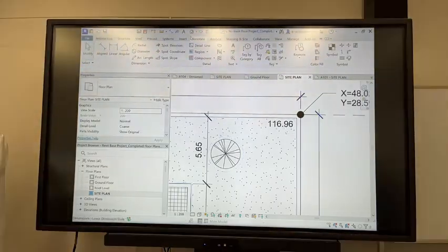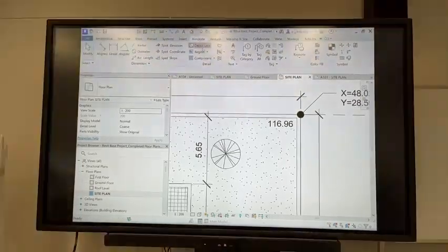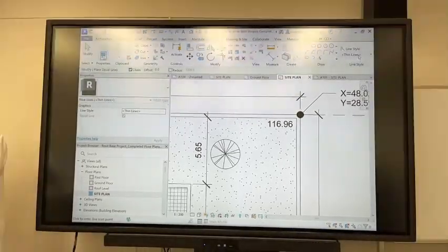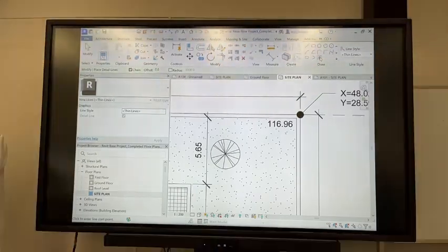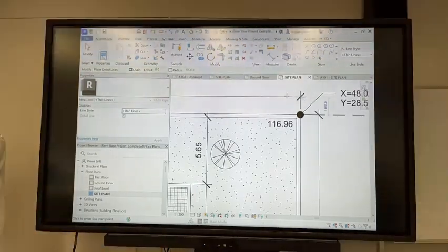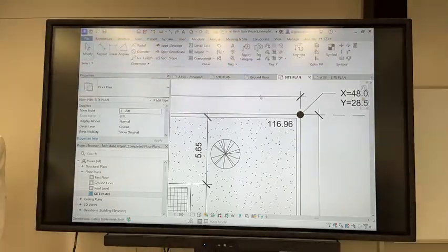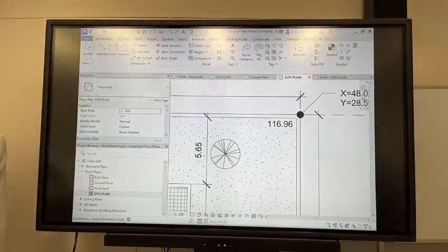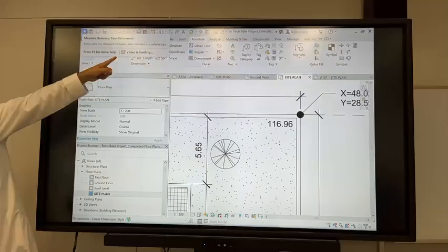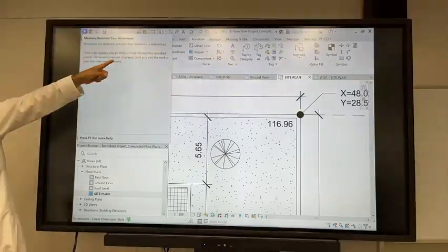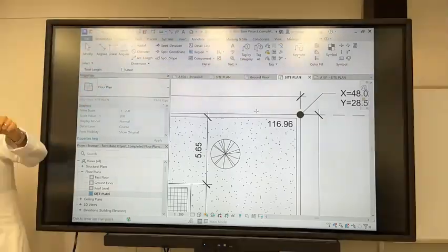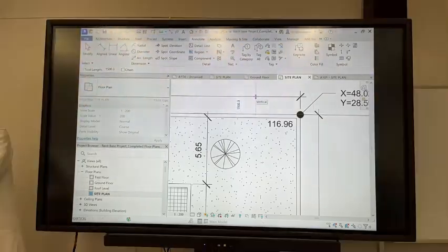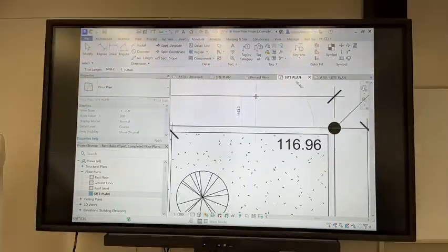You can do a detail line, annotation, detail line. You can do an offset. You measure it. This up here gives you a quick measurement dimension. Oh, you see that little ruler? So you check the dimension here. This is around a meter and a half. I see that it's suitable. Okay.